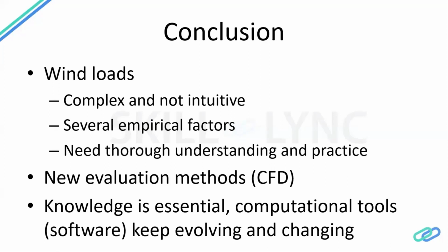And that's why it needs thorough understanding. If somebody has designed a chimney and has not put in those helical strips to break the wind flow, then however diligently you have done the design, if the understanding of that particular effect is not there, then you might be constructing an unsafe thing.